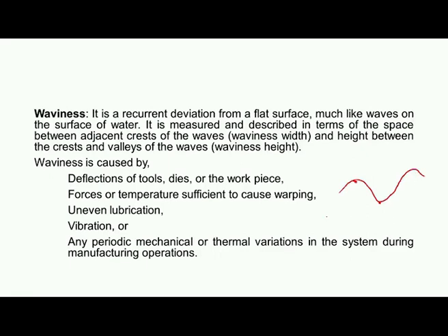This waviness is caused by deflection of tools and workpieces. For example, we have the workpiece mounted between two centers, and when we use the cutting tool and press, if the workpiece is slender, it may bend like this.